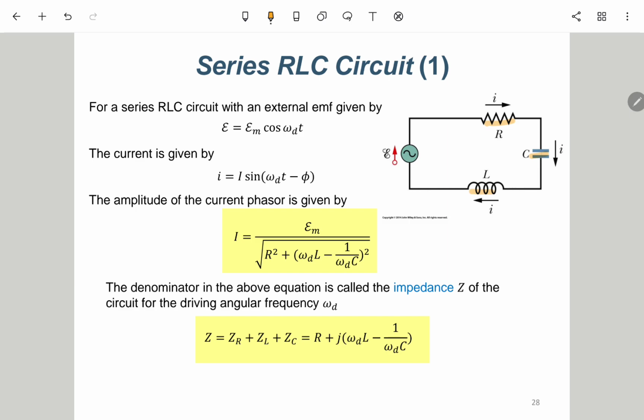If the impedances are in parallel, we need to take the reciprocals, add them together, and take the reciprocal again. One thing to note: for resistors and inductors, series adds directly and parallel uses reciprocals; capacitors are the other way around. But for impedance, series just adds up. We have series RLC, so we add the three impedances together.